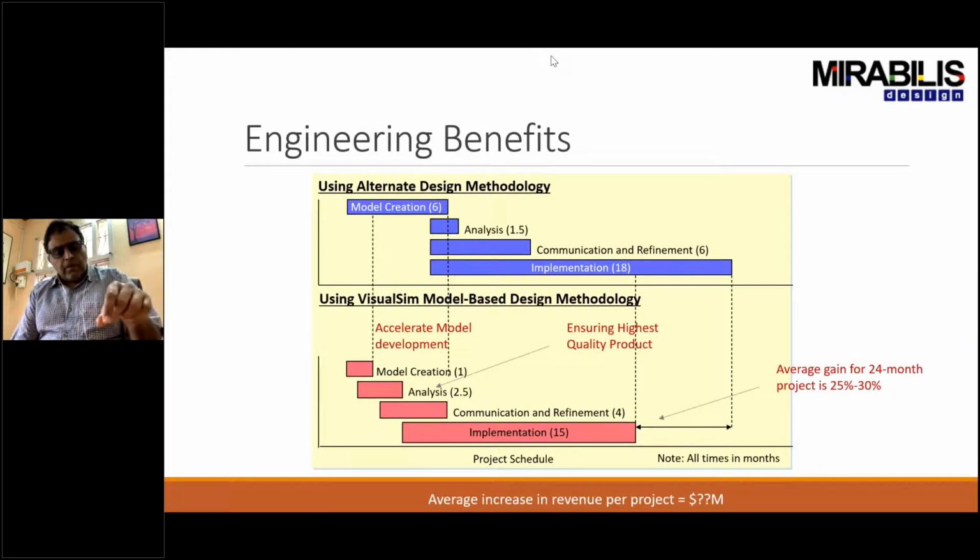And processing each one of these data sizes with the specific function. So we know what the data size coming in is, we know what the reads and writes to memories are, and we know approximately what the latency is to do the processing on the FPGA or on the processor itself. So using that, you can get fairly good accuracy.